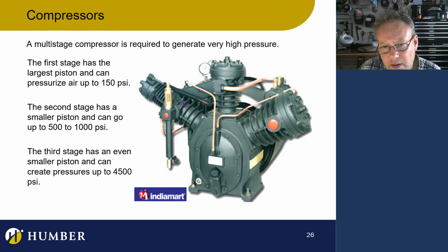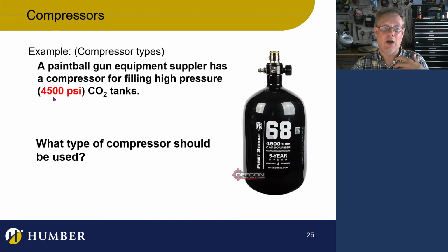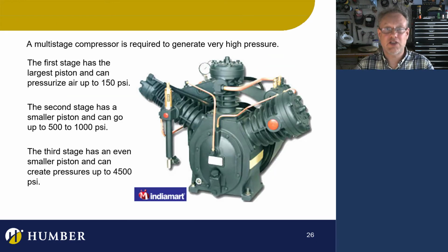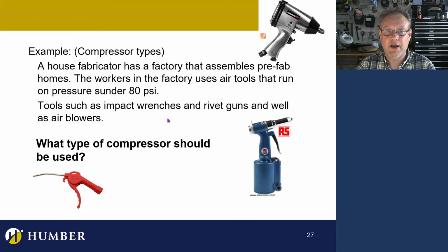I don't know, I think it's not an intercooler. I think these are the cooling jets, maybe coolant goes in here, because I know that to compress air down to 4,500 PSI, you need to physically remove heat. That's how you do it, because it gets really, really hot when you compress it that much. So it's a triple piston compressor.